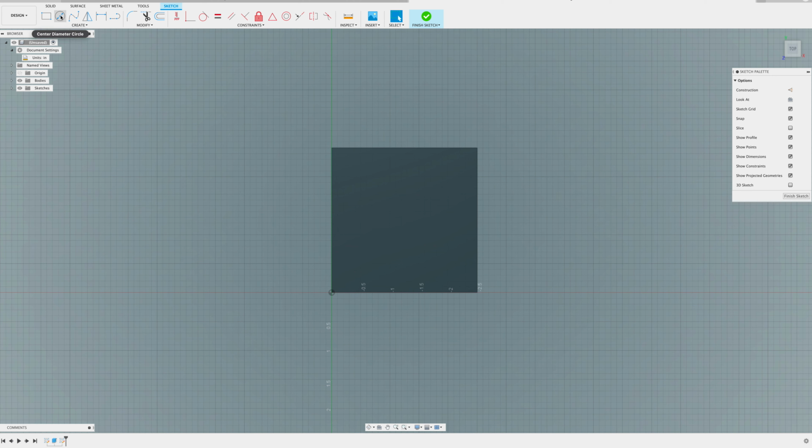To do that, I'm going to draw a circle, and I'm going to pick the center of the object. You'll notice I've got that little dashed green line coming over from the center, but how do I know where it is left and right? We called this polar tracking before. If you come up here and get that little triangle, and then start coming down, see how the green lines start showing up, and then when I get to here, the other green line will show up.